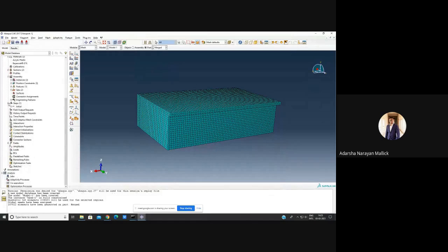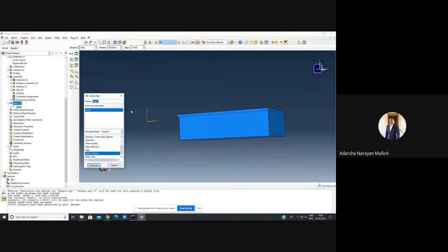Then I am going to assign the steps. Here the step is kind of force. We have to put the gravitational force or pressure energy, what kind of force we want, we can use here. So for that step we have to double click or right click and create. Now I am going to first put the gravitational, because the fixed portions, the four boundaries and the bottom part will be fixed and the upper part will be only inflated. So for that I am putting that gravitational force.